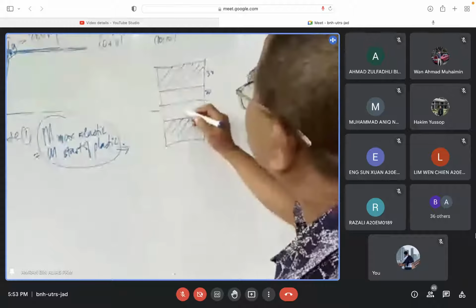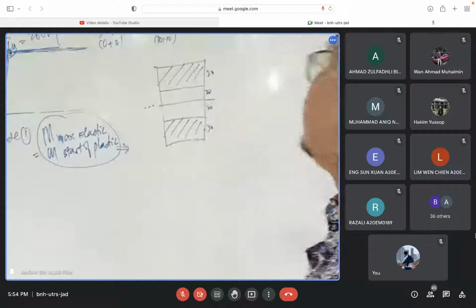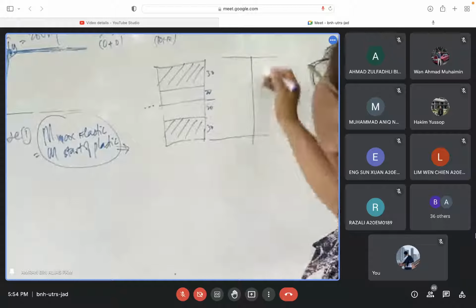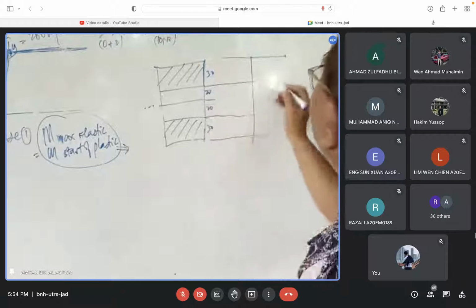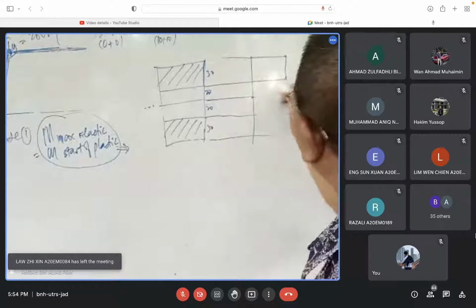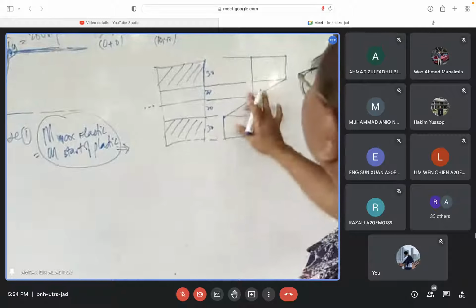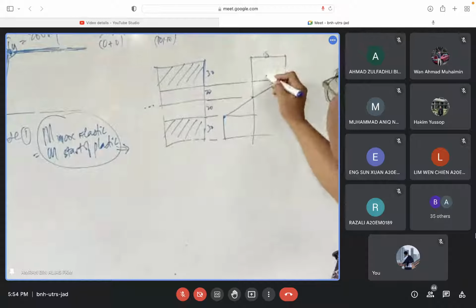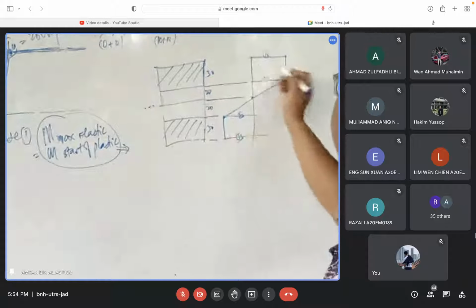So this is plastic, this is elastic. So this is still elastic. 20 elastic and 30 plastic. So the diagram of the stress will become like what? You have to draw this confidently. 200, maintain until here. So maintain until 200, and then only then a straight line there. Just a straight line there. So these are the stress diagram. Sigma y 200, sigma y 200, all the sigma y there.